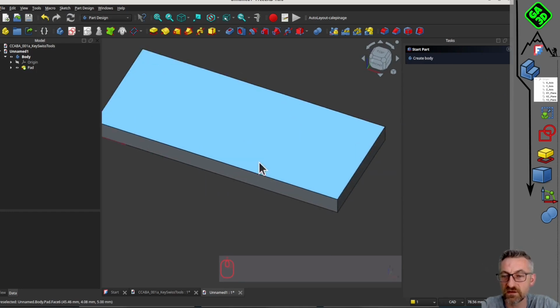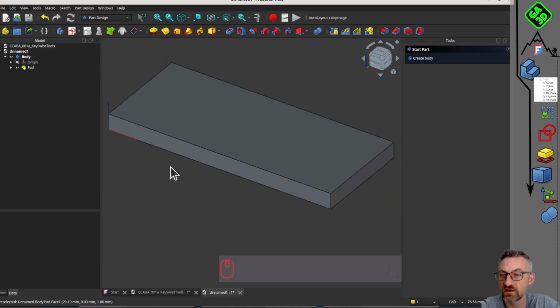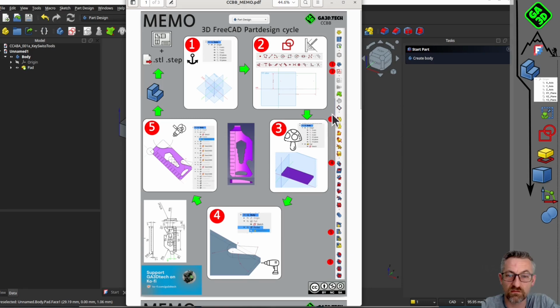By default, it is 10 millimeters high. Here, my small tool will be only 5 millimeters high, so you change the value. Click OK, and there you go. You've created your first volume. So whatever you do in 3D construction, you always have to go through these steps. Of course, in general rules, there are always exceptions. Let's say in 95% of cases, the 3D design workflow will follow these steps. So the definition of references, the definition of geometry, the creation of volume.